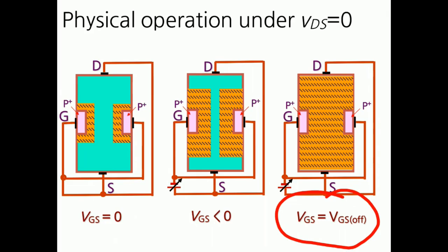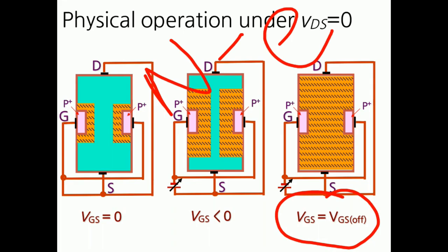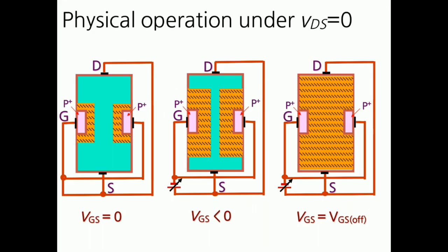And friends, you have to remember the FET is a higher version of the BJT, bipolar junction transistor. In a BJT, both holes and electrons are required to flow the current. Here only one, either hole or electron. If our FET is N channel, then only electrons participate in the current. If our FET is P channel, then only holes are required to flow the current between drain and source. So this is about the FET.